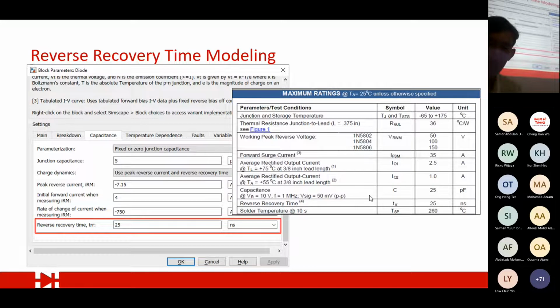Okay, for example, how do you know? Then you can look at the data sheet again, the reverse recovery time. See, the reverse recovery time, 25 nanoseconds. Okay, it's nanoseconds, so anything running in megahertz shouldn't be any problem. You put 1 over time, you get the frequency, right? That actually tells you that if you apply a frequency higher than this, the diode will not work properly.